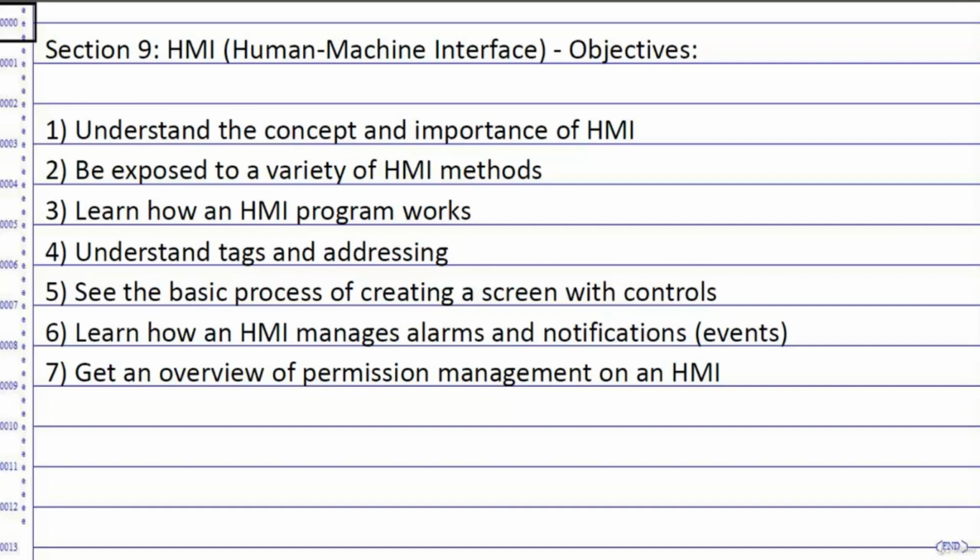If you want a percentage input, it should be from 0 to 100. You don't want an operator to be able to come along and enter -6,000. Who knows what that's going to do to a running program?